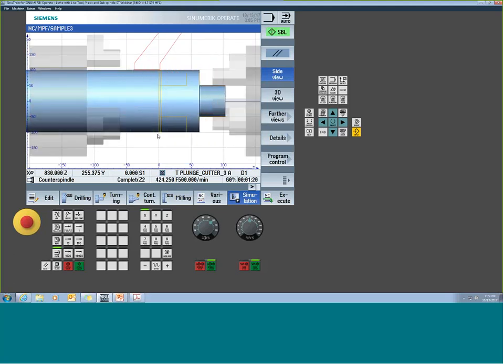So how far out did it pull? Well, it knows that you told it the part is sticking out 60 millimeters in the header page. So it knows it has to pull it out 60 mil. There's nowhere else it could pull it out to, right? Because then it's not going to be consistent. So it starts doing that calculation for you. So that's how it knows. So it's going to pull it out to 60 mil,